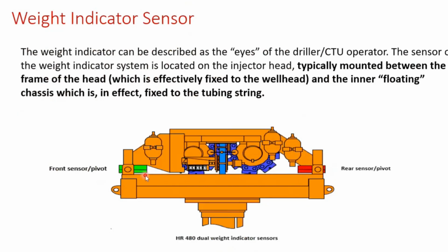If the resultant force is negative, because we will see the equations after that, because we subtract some terms from the coiled tubing pipe weight, and these terms are larger than the coiled tubing weight, especially at the surface, where the coiled tubing weight is the minimum weight, then the other factors may exceed the coiled tubing weight and make the resultant force negative.